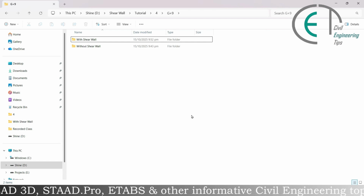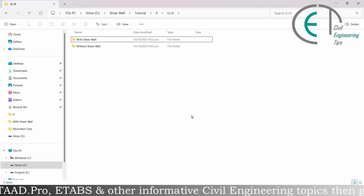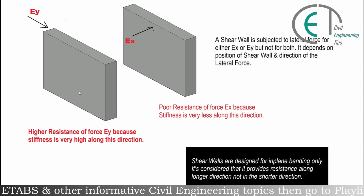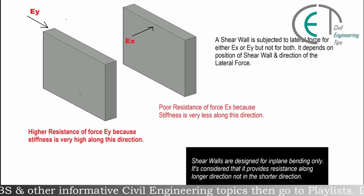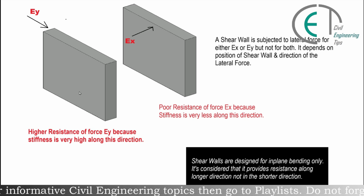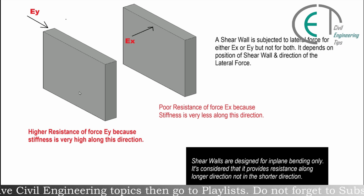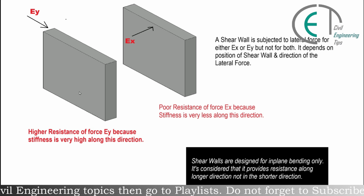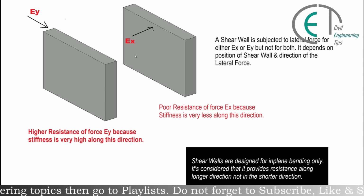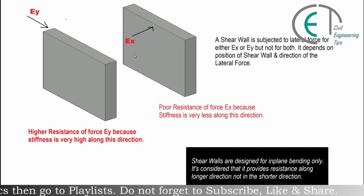Using shear wall is not a solution by itself. You have to know how to place that shear wall in the building, and then you will get maximum benefit from it. Let's discuss the first figure. Here we have placed the shear wall along the direction of seismic force in Y direction, and in this case we are getting higher resistance to force EY because stiffness is very high along this direction. But if we consider earthquake force along X direction, then we will get poor resistance to force EX because stiffness is very low along this direction.